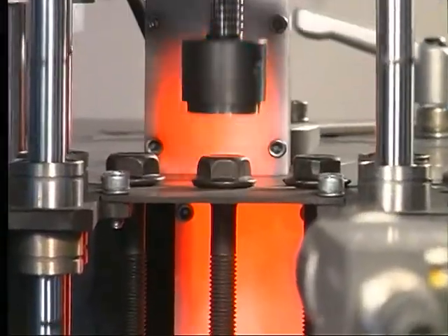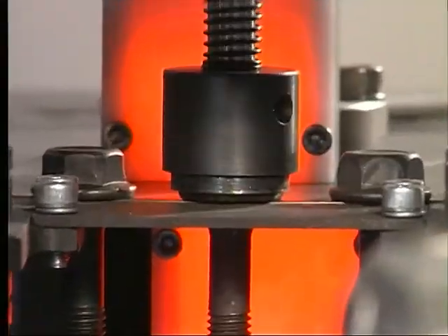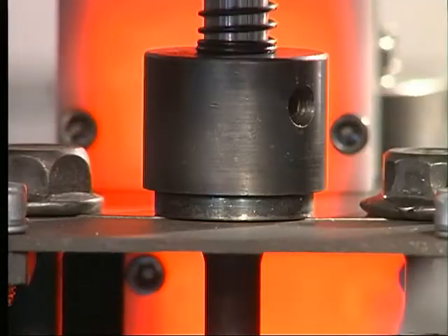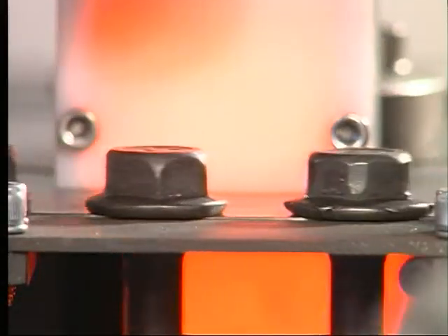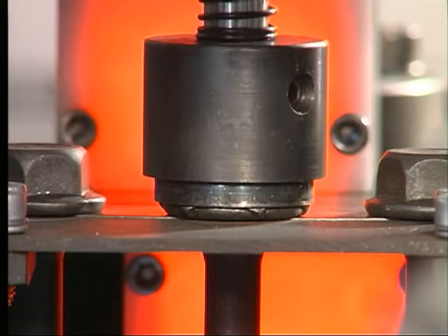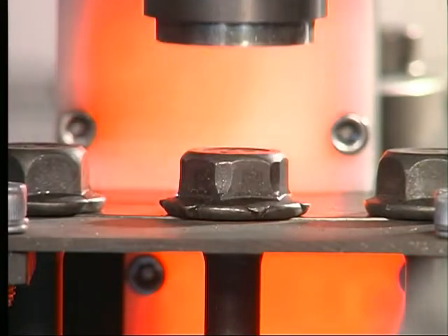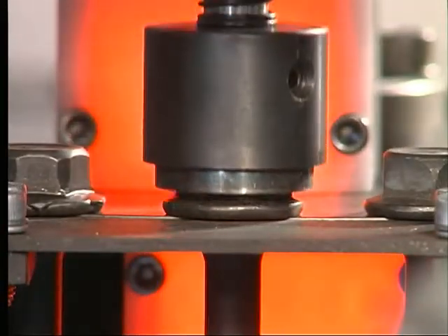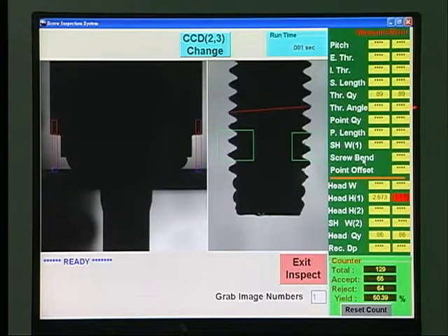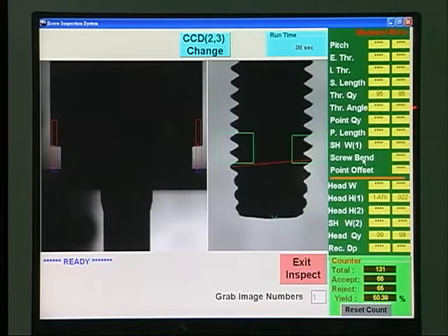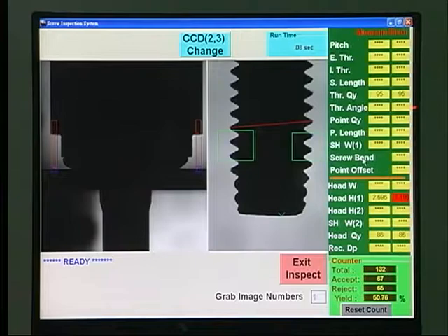To inspect the height and shape of the screw head, use the press head with an appropriate socket, combining the measurements of the height and shape of the head. The program can screen out screws with distorted heads, missing friction rings, or distorted cover positions.